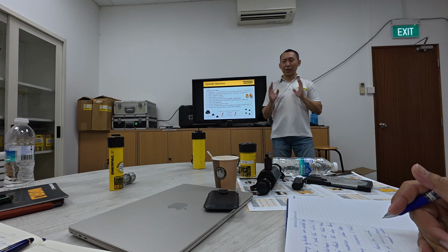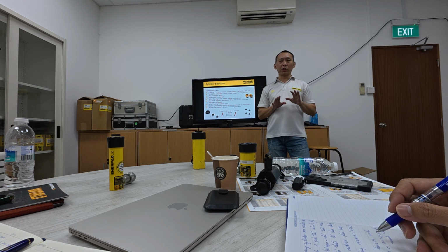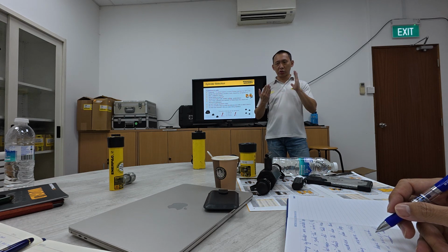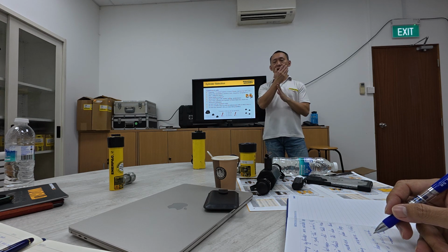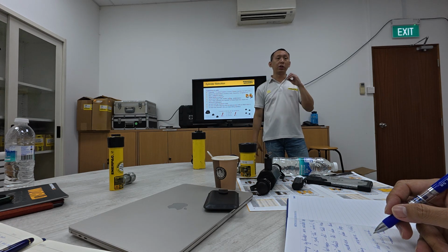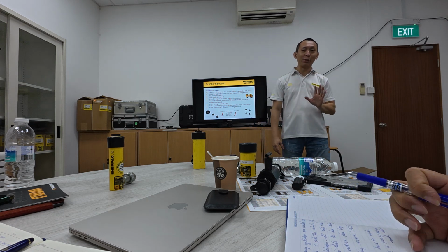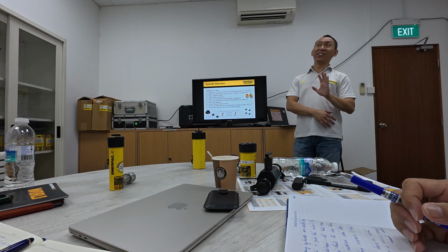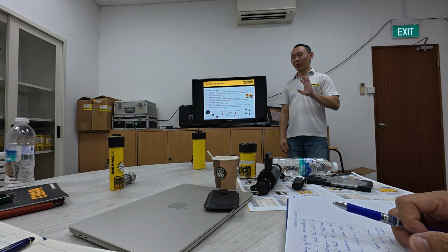But as much as possible, we don't want them to get this side load, because once you have side load, you scratch the ball and then you will start to leak. And in the worst case, with extreme side load, you will damage the body. So we tell customers zero side load is the best. Don't tell them they can take 10, they will try to do funny things. So always tell them zero.